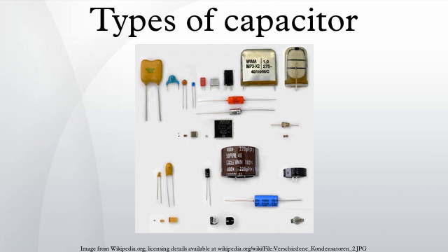Frequency dependence. Most discrete capacitor types have more or less capacitance changes with increasing frequencies. The dielectric strength of Class II ceramic and plastic film diminishes with rising frequency. Therefore their capacitance value decreases with increasing frequency. This phenomenon for ceramic Class II and plastic film dielectrics is related to dielectric relaxation, in which the time constant of the electrical dipoles is the reason for the frequency dependence of permittivity. The graphs below show typical frequency behavior of the capacitance for ceramic and film capacitors. Frequency dependence of capacitance for ceramic and film capacitors.